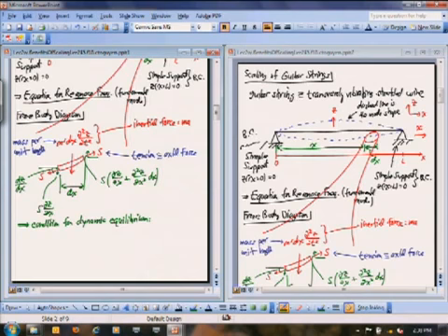So this is going to be plus second derivative of z with respect to x times dx, and then minus the other force component, S times dz/dx, minus the inertial force, m prime times dx, times second derivative of z with respect to t, and all those have to be equal to 0 if I have dynamic equilibrium.